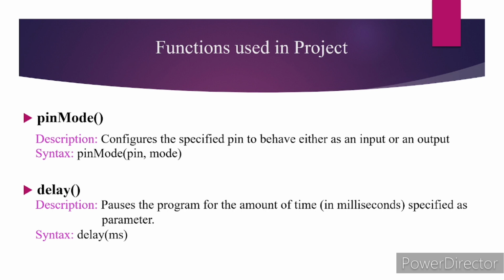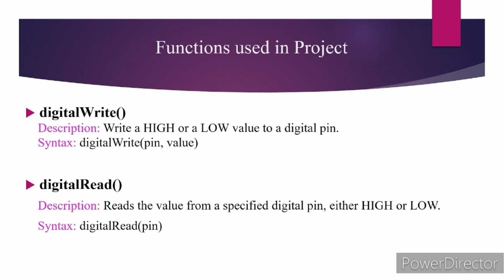The functions used on LED are pinMode, delay, digitalWrite, and digitalRead. pinMode configures the specified pin to behave either as an input or an output. Delay pauses the program for the amount of time specified as a parameter. digitalWrite writes a high or a low value to a digital pin. digitalRead reads the value from a specified digital pin, either high or low.